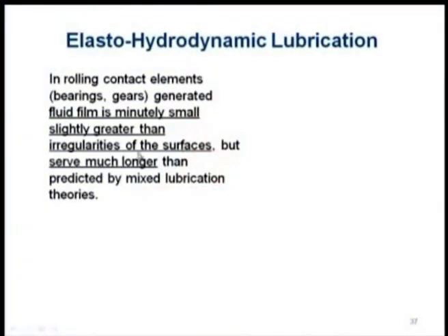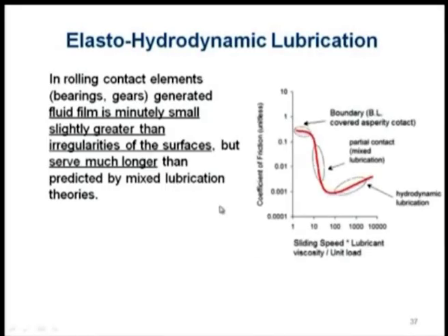Theoretically we are not able to get the results if we go ahead with the simple hydrodynamic lubrication mechanism. However, we will be treating that in the next module, when we exclusively come up with the Reynolds equation and the elasticity equation and try to solve the equations. If we use only the hydrodynamic action, then the film thickness will be much lesser, but in reality when we do experiments we find the film thickness is greater than that. And this is what we are talking about, this domain somewhere here, elasto-hydrodynamic lubrication. It is not reaching hydrodynamic lubrication; the bearing number is not as high as required for hydrodynamic lubrication.